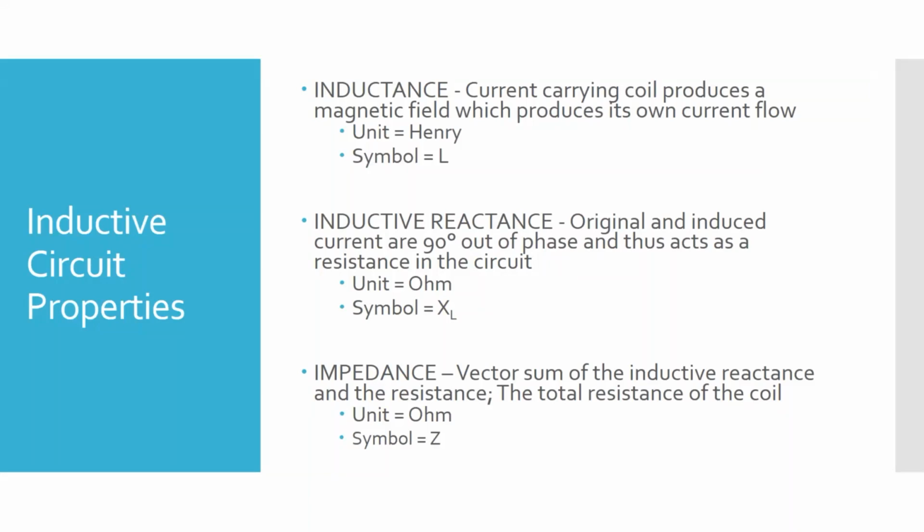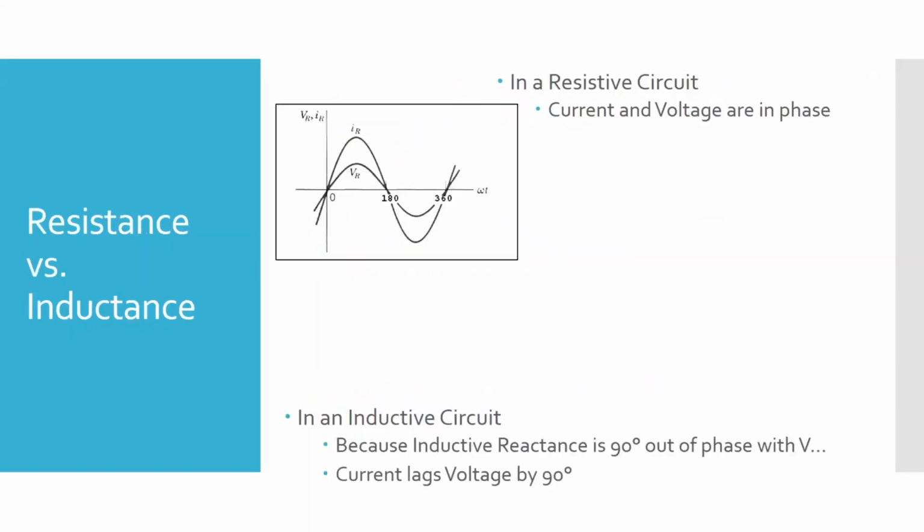And what we're going to use is these three things as we move metallic objects closer to or away from a coil, or put more metal in front of it, or remove metal in the form of a crack in front of a coil. That's going to change the inductance and the inductive reactance. And that change we can measure, and it can be used to indicate when the amount of metal in front of a coil changes, or if there's a crack or corrosion.